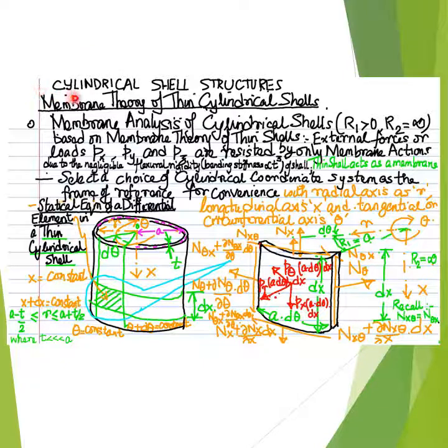The solution of the unknown internal actions, that is the 4 unknown internal in-plane or membrane actions Nx, Ny, Nxy, and Nyx, and the 6 unknown internal plate actions or out of plane internal actions, that is Mx, My, Qx, Qy, Tx and Ty, is to be completed by applying the fundamentals of mechanics.